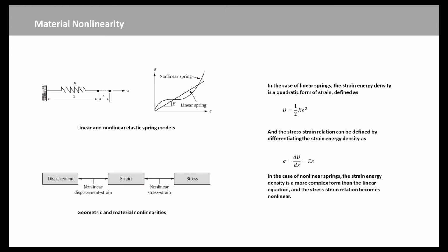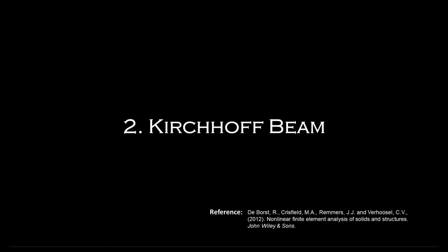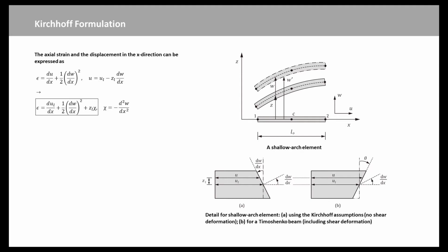In the case of nonlinear springs, the strain energy density is a more complex form than the linear energy equation, and the stress-strain relation becomes nonlinear. The majority of this video is devoted to two-dimensional beam elements. Beam elements for two-dimensional analysis are of interest in their own right, but also have a didactic role.